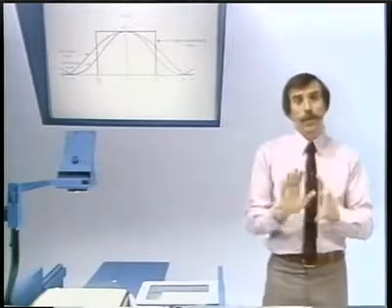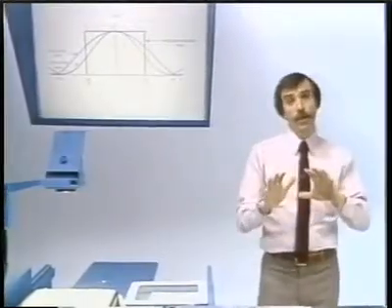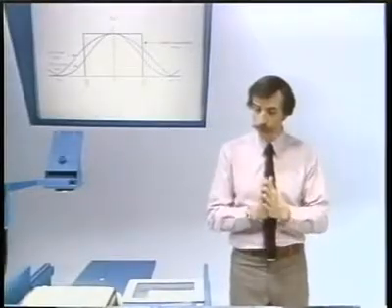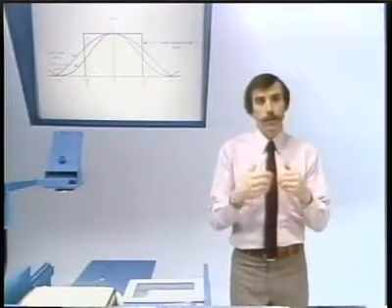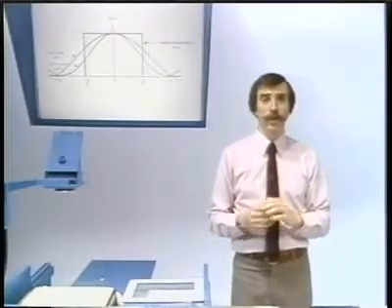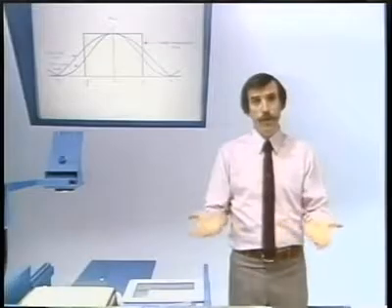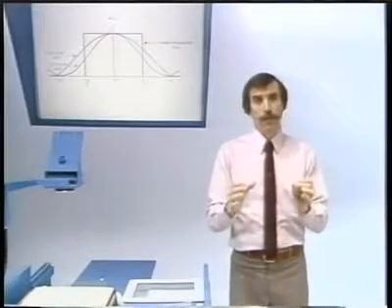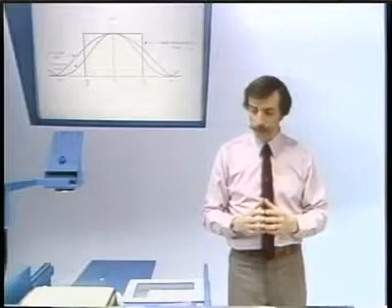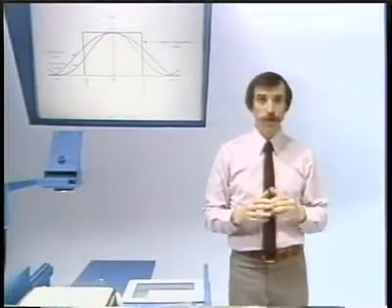Well, to illustrate some of these ideas and the notion of doing reconstruction with a zero-order hold or first-order hold, and then adding to that some additional low-pass filtering, what I'd like to do is illustrate sampling and interpolation in the context of some images. An image, of course, is a two-dimensional signal. The independent variables are spatial variables, not time variables. And of course, we can sample in both of the spatial dimensions, both in x and y.